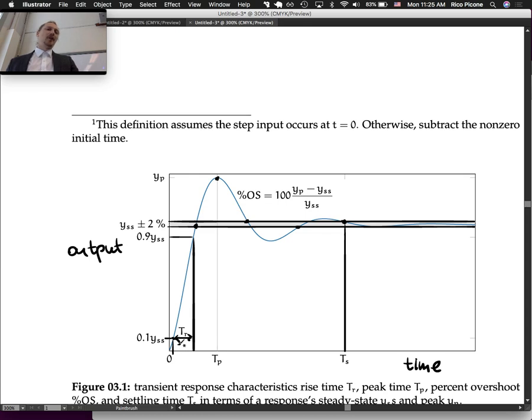So the time constant you could associate with it, which is not typically done for a second order system, is the exponential envelope that this damped oscillation follows. The damping ratio is going to govern how much overshoot you have, right? This looks to me like maybe a 0.3 damping ratio, but I'd have to go back and look at some examples to be sure.